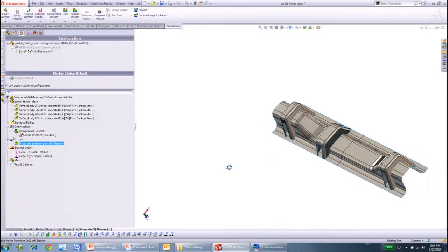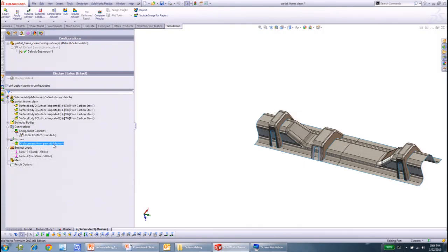And it will add a new item to show you where it transferred the loads, the displacement fields, from the common edge or face between the parent and the submodel. It brings in one feature which will contain all that information to pass on to the solver, which will be these edges.